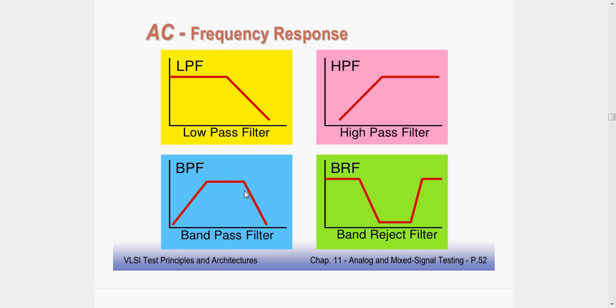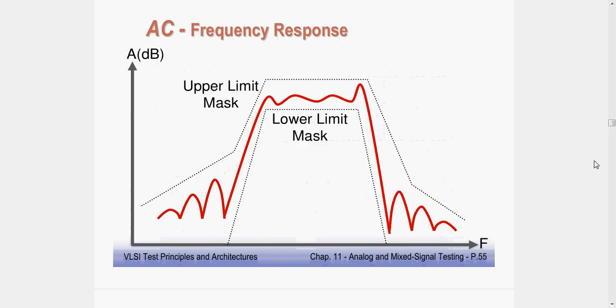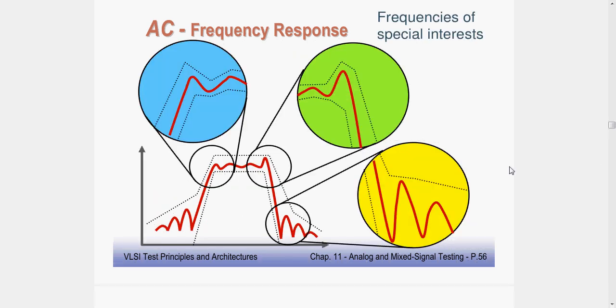But when we go for a practical waveform, what happens? We have a particular amount of peak overshoot and a damping factor. These things have to be considered, and we need to go through the methods for mitigating them. That's why we are going for frequency response.